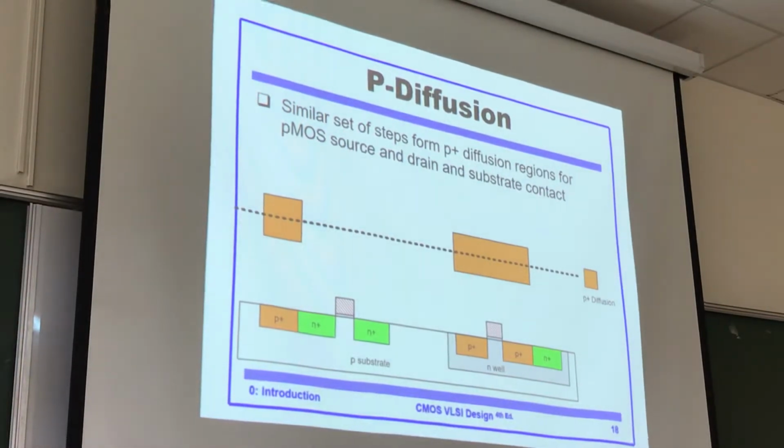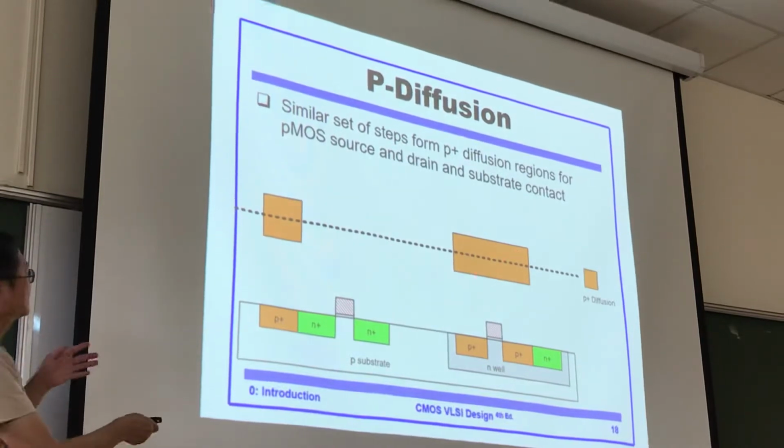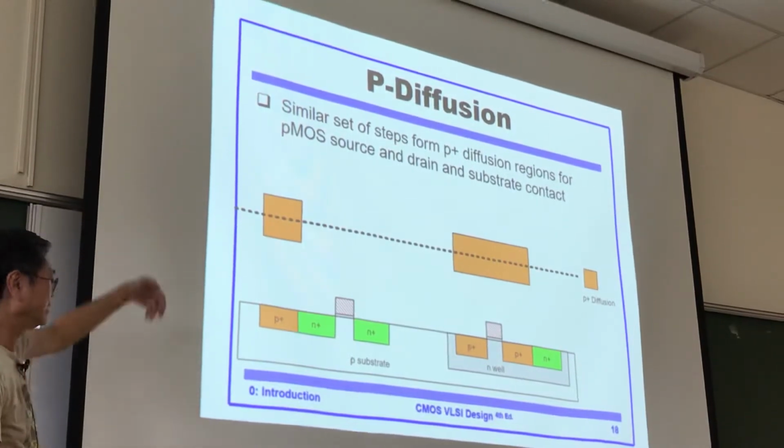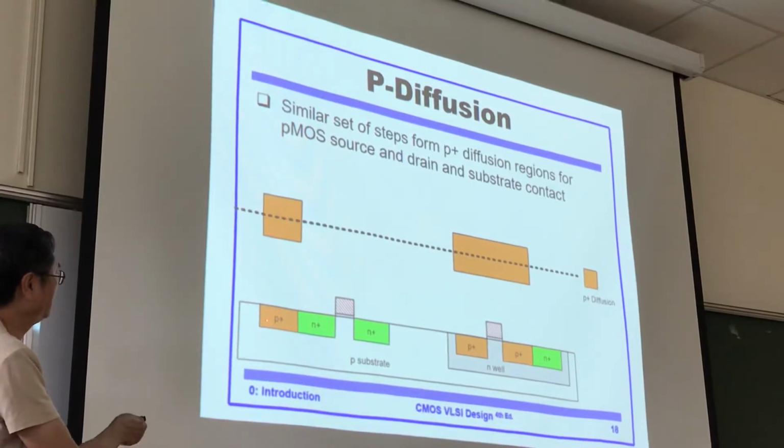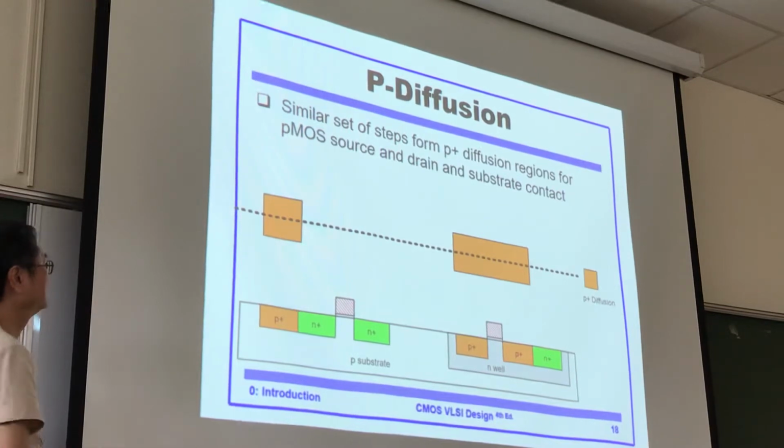Sitting between the ion implantation emitting source and the chip, only at this mask opening can the ion beam go through. So it implants into the silicon right here and gets P ion. So this part has no diffusion on this side.